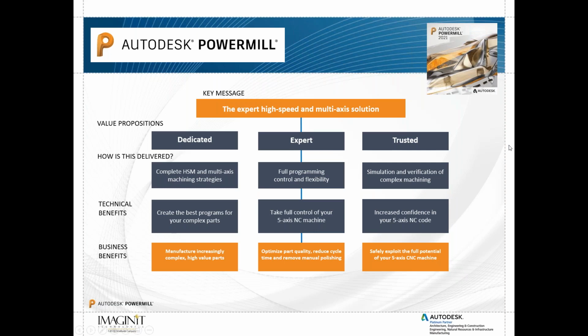The last really important thing with PowerMill is that it has some of the best collision avoidance capability in the suite. The collision avoidance technology checks for collisions when you calculate the toolpath. When you first generate your toolpath, it'll look for collisions between the tool and the holder with your workpiece or with your fixture. It's also going to check a second time when you simulate.